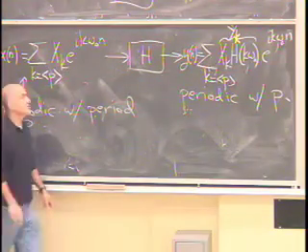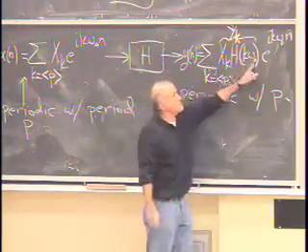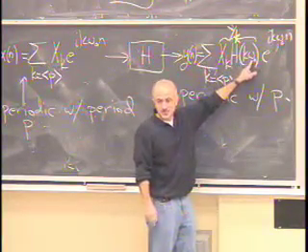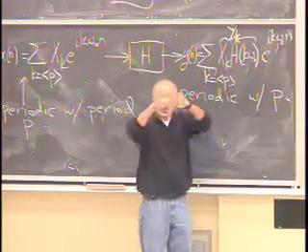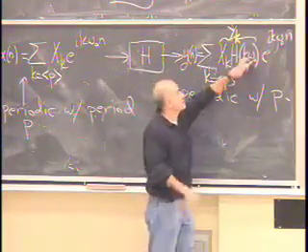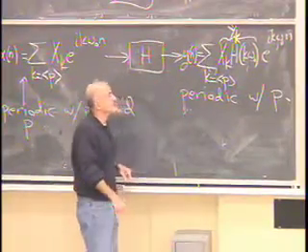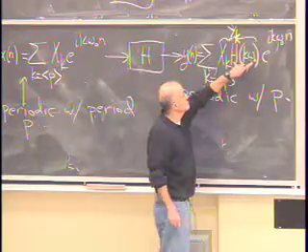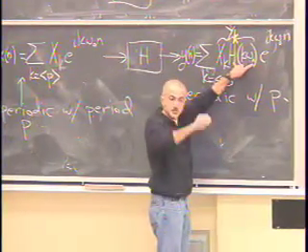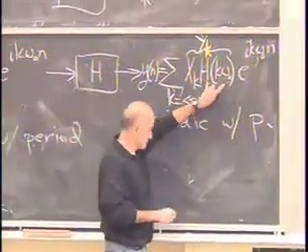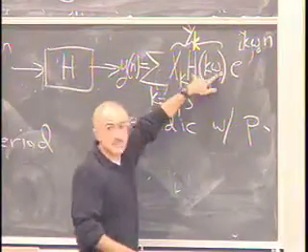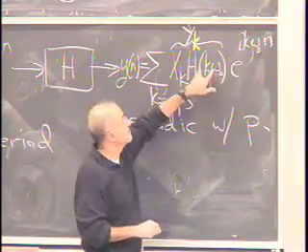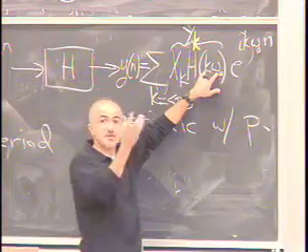So your audio equalizer essentially is this H of k omega naught. It picks a particular set of frequencies. Now, of course, it's not exactly one frequency. It's usually a set of frequencies around this, because that's dealing with analog signals. But essentially, when you turn up and down the knob for each frequency band, it's this H of k omega naught that's going up and down in magnitude. And that's how you get rid of certain frequencies and how you amplify certain frequencies.